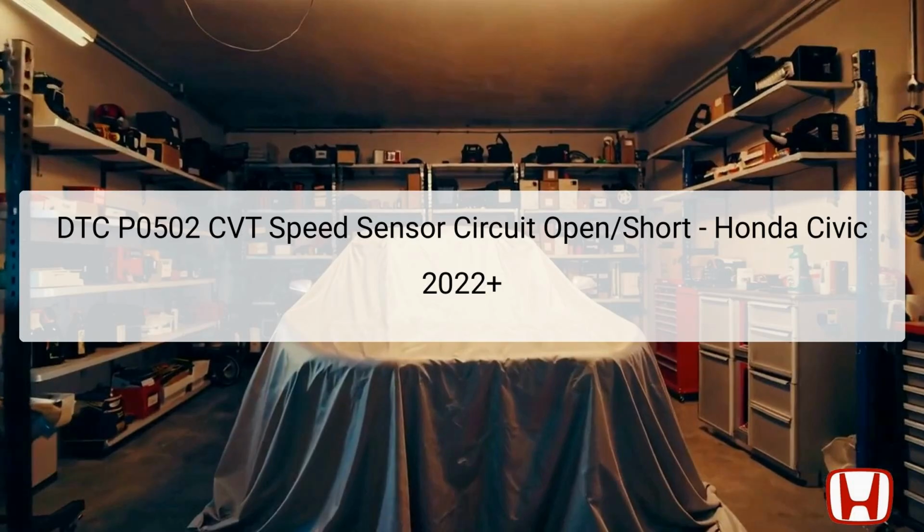CVT stands for Continuously Variable Transmission, which allows the engine to operate more efficiently by providing a seamless range of gear ratios. The TCM, often located near the transmission assembly, relies on several circuits, including VCC3, VEL-PWM, and SG3, for the smooth operation of the transmission system. If the TCM detects an issue with the CVT speed sensor, it triggers this diagnostic trouble code, indicating an abnormal condition in the sensor circuit.